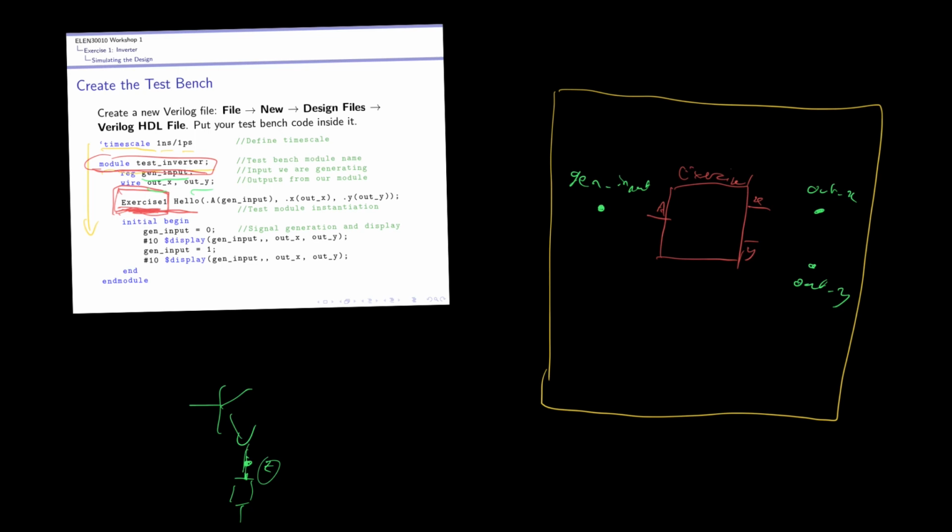So these are just junctions. Sometimes we call junctions wires, sometimes we call them registers, REG. Verilog's a bit funny, that'll become clear later on, but for the moment, just think of these all as nodes or junctions that we can use to wire things up with.